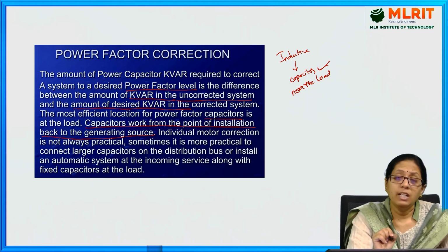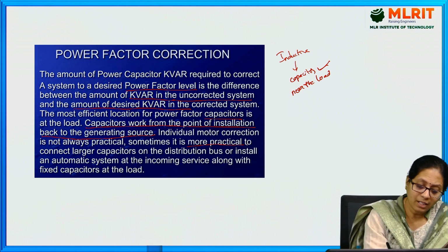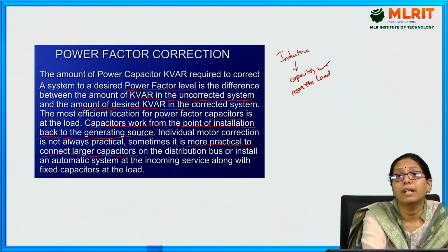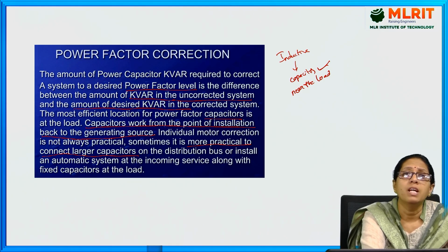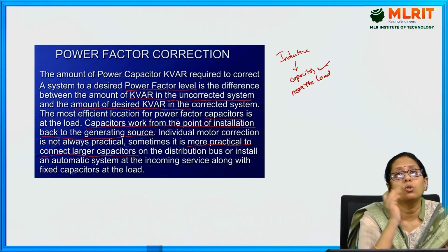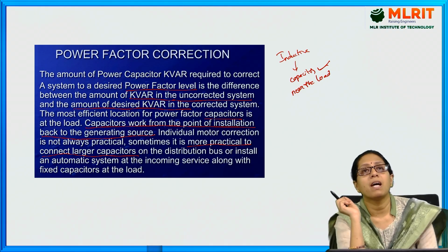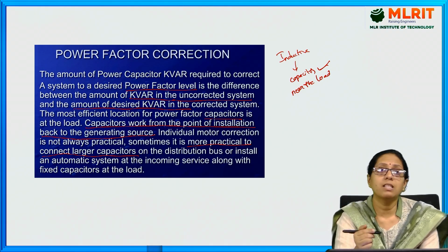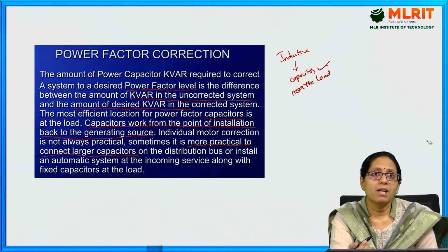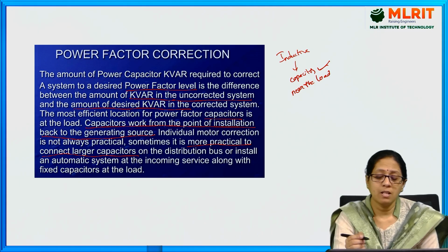Individual motor correction is not always practical. Sometimes it is more practical to connect larger capacitors on the distribution bus. During distribution also, we sometimes need to connect capacitor banks. When a number of capacitors are connected in parallel, you call it a capacitor bank.